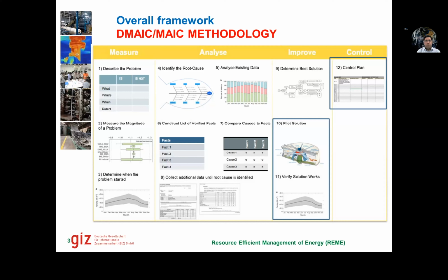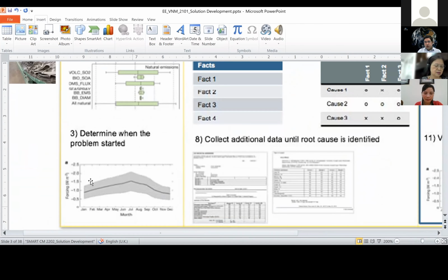So we keep on monitoring it. Probably again the problem is in monitoring. So we keep on monitoring, and with the evidence that there are leakages, and with the evidence that this data gap is increasing, we can safely recall that 1 month ago we had a 0.5 ton per hour gap, and probably 2 months ago we had a gap of only 0.25 tons per hour. So that is how we can estimate where and when the problem started. Don't look at these graphs at the moment. These graphs are only there as an example. At the moment I am just showing you the stages.